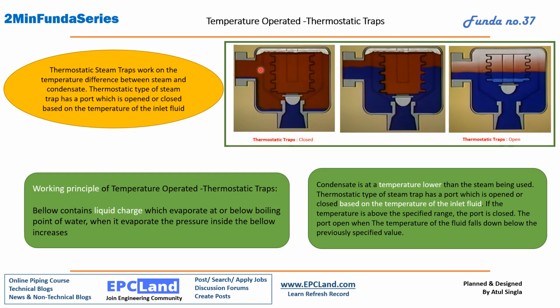If steam is entering, this charge inside the bellow will evaporate, increase the pressure, expand, and close the valve. Again, when condensate is coming, with the course of time the steam inside the bellow will start condensing, the temperature inside the bellow will start decreasing, and more condensate will be formed, with less steam and less pressure, so this will contract and the valve will open. So based on the temperature of the inlet fluid, if steam is there, this will expand; if condensate is there, this will contract. It closes and opens based on the temperature of the inlet fluid.